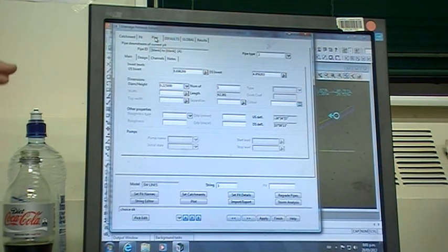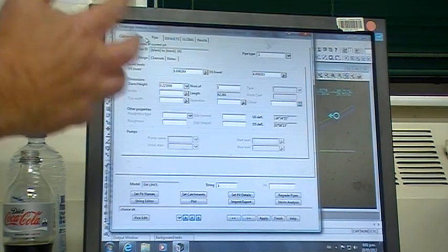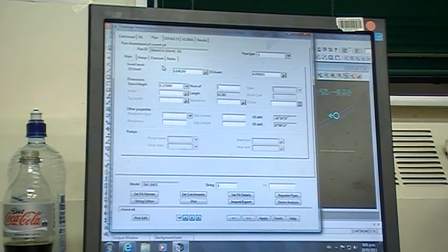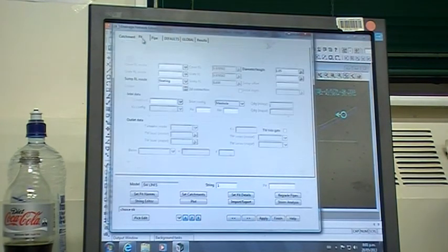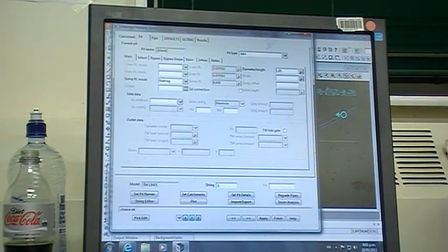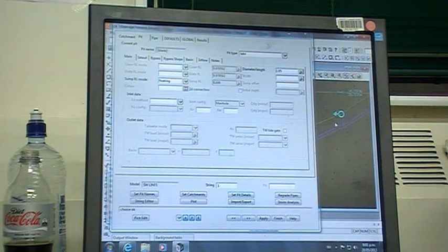And I'll just run through and show you all of those things, which can then be individually manipulated for an individual pipe, an individual pit, or an individual catchment under the next 3 tabs. So it'll take the default first, and then if you set something specific on one of these tabs, it'll overwrite it. For instance, under the pipe tab, if I changed a value in here, it'll overwrite the defaults for that section of pipe between the upstream manhole and the downstream. If I click on the pit, it's the same thing. It will change the values for that individual manhole.